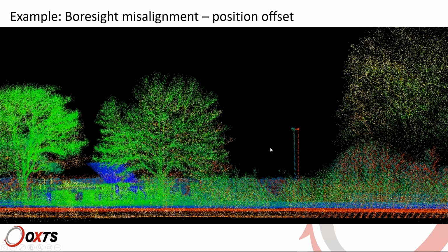And because it's a single pass, you don't have a problem of a double vision, but what you have is an offset in position. In a similar way to when we've seen the SPS scan, in this case, because you have a misalignment, because you have an error in the orientation of the system, the position of the lamppost is not correct. It should be on top of this blue one, and it isn't, even with a single pass.